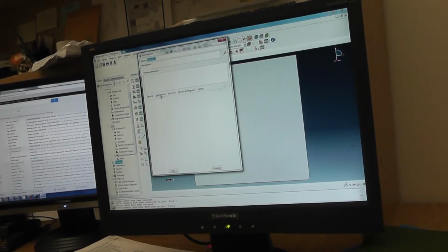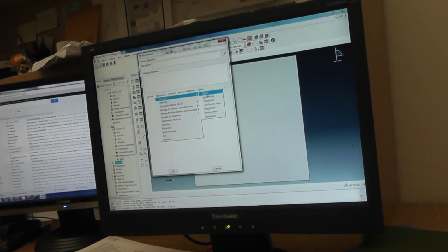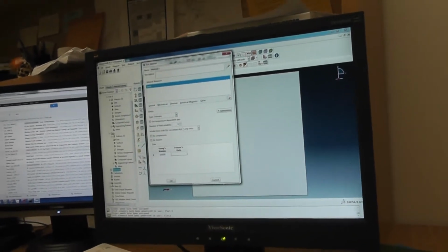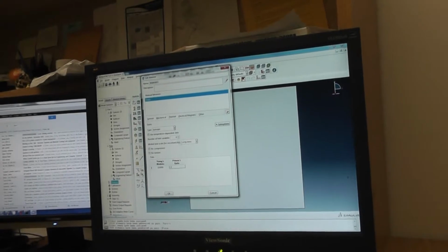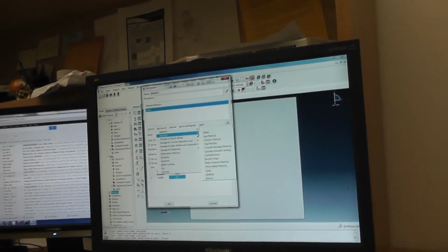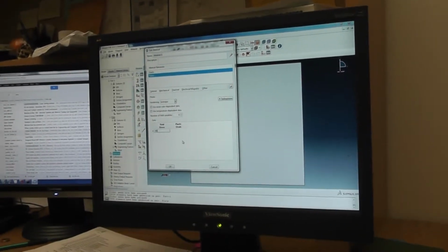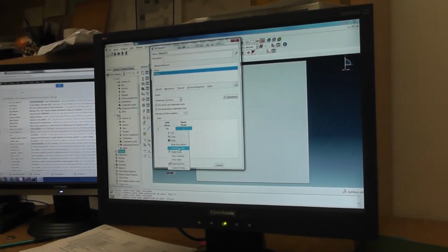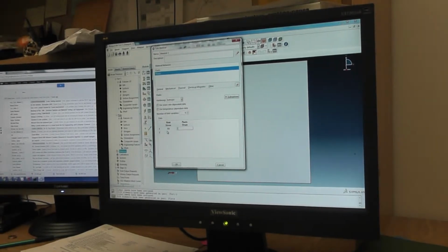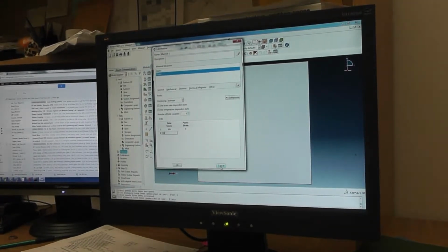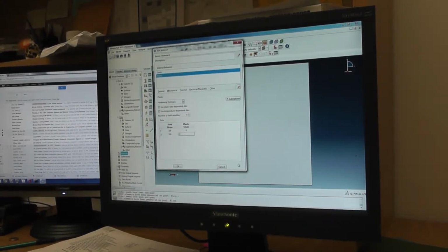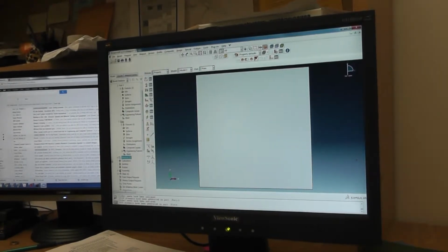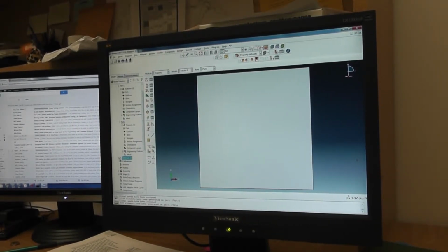Material. And I am going to have one material, so elasticity. It's first 110,000 MPa, 0.3, and the plastic 300, 0, and you insert your stress strain curve, and let's say it's all linear, but in your case it's not going to be linear, and let's say up to 30% strain. So depending on the stress strain curve that you obtain.